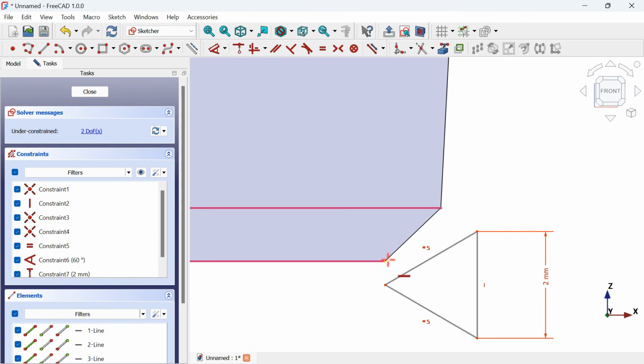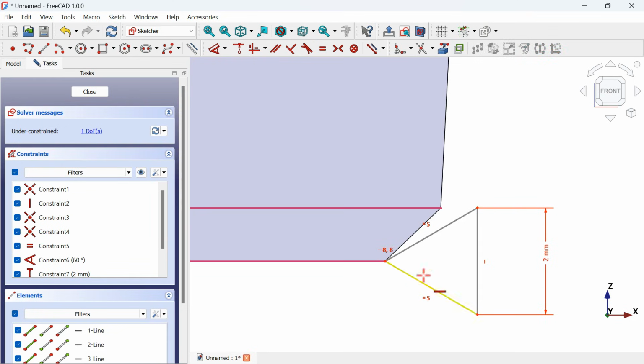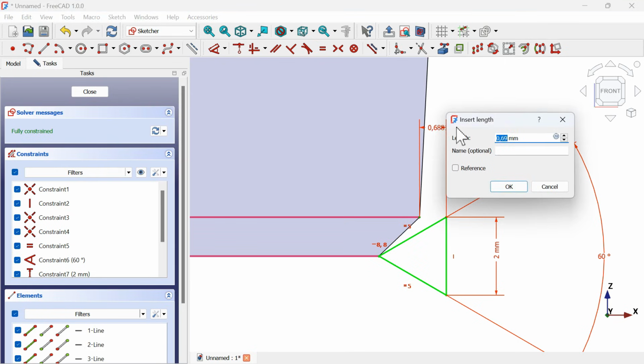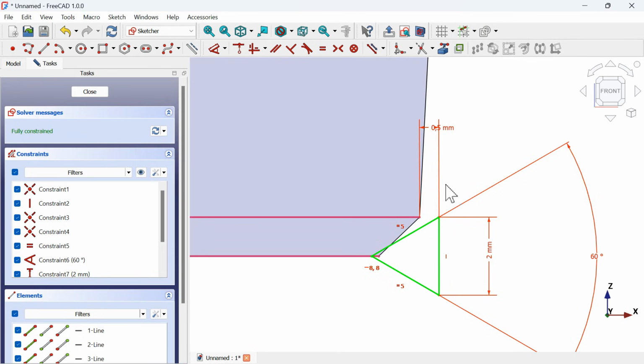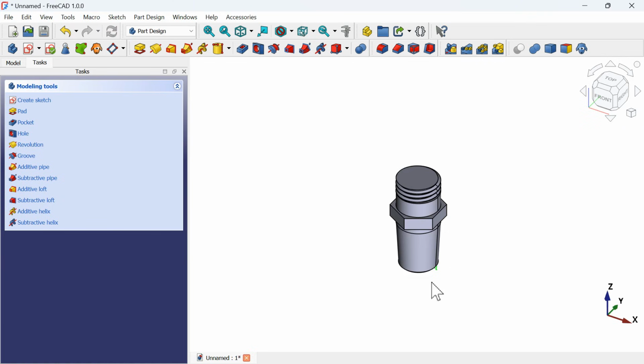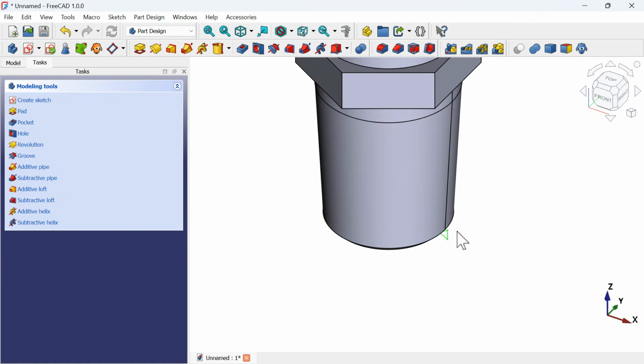What you'll do with this is to make these two points horizontal, constrain it, and next you'll use the dimension tool to set the distance between this point to this point here, and we'll set a distance of 0.5 millimeters, and here I have this. Now skip 2 times to leave this sketch, and if we zoom in now we can see this geometry.